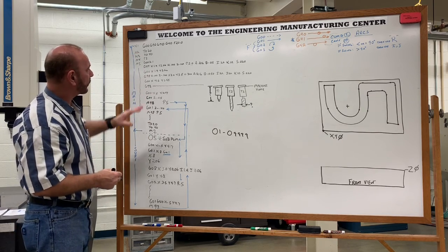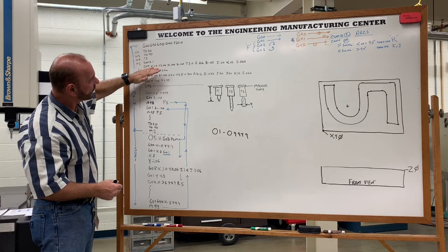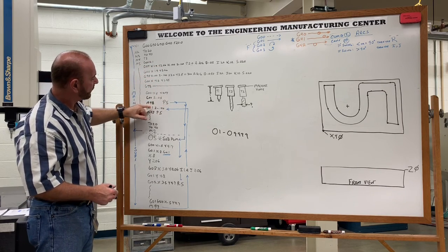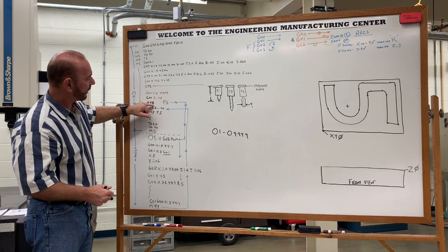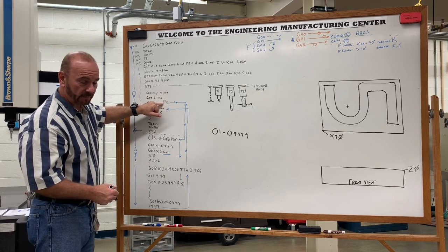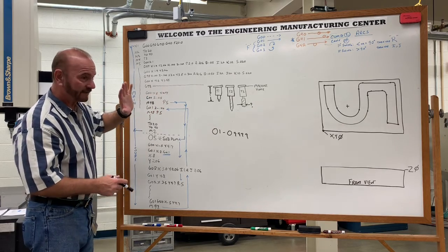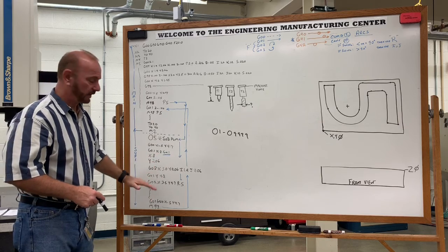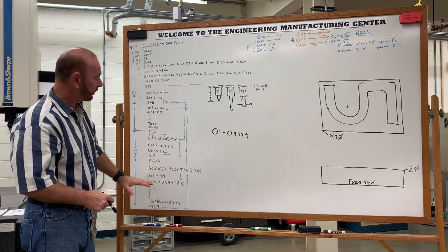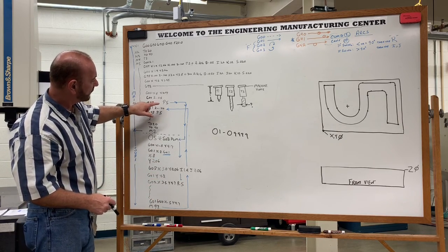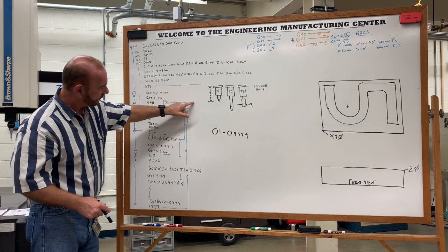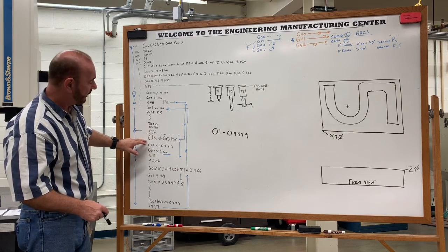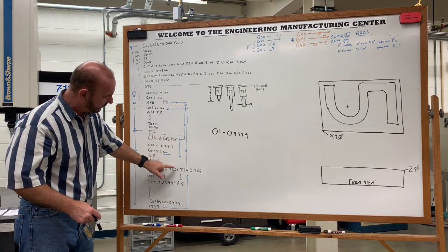And the way that it works is as the main program is running and executing its commands, the command M98 P5 tells it to call a subprogram, program 5, and that's the one that's going to actually be called. It doesn't have to call 1 and then 2 and then 3. It can call any one of the labeled subprograms that are below it. So what happens is the controller then leaves the main program and searches down through the other list of programs, finds program 5 and then executes all the movements in 5.